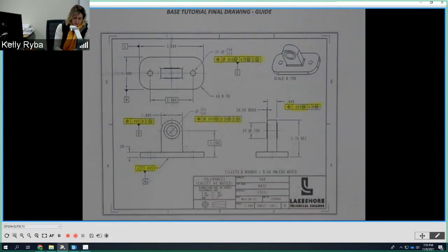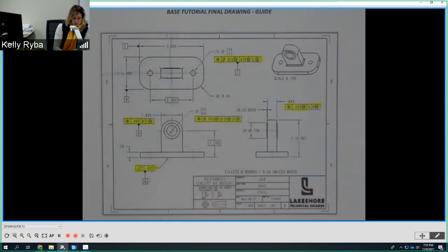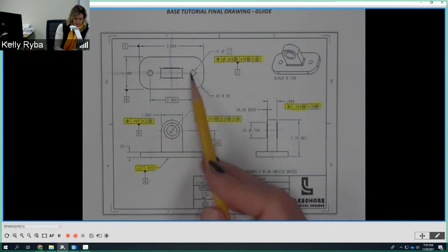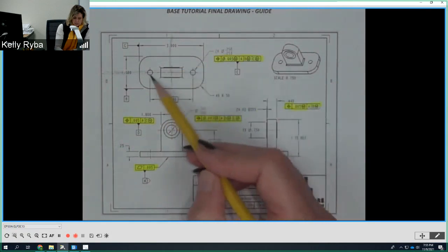So we're going to position to this dimension, okay? We're also going to position the 1/2-inch hole that's going through, and that is also going to be positioned on the center of the ear. And then it's going to share the same center line or be perpendicular to the center line that is created between those two holes there.